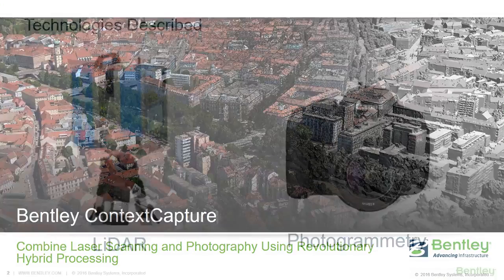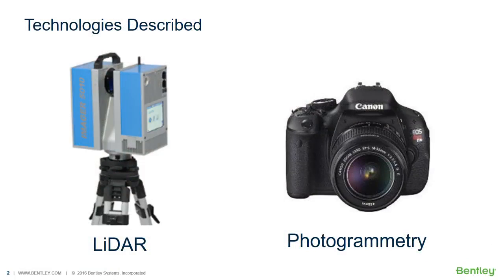Like I said, first we'll talk about describing the technologies. You don't need a full understanding of this to understand how the algorithms work, or basically photo-based acquisition. We need to focus on overlap and several things that I'll cover today. One technology is LiDAR. LiDAR is collecting of point clouds. So basically, a laser is going to go out and measure distance and angle, come back and give you an XYZ location. It's very accurate, but it does cost a lot more money.